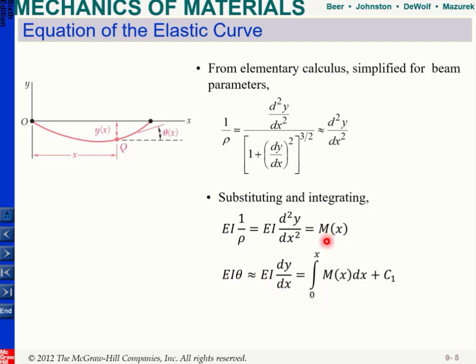And so if you take the integral once, I need to integrate from 0 to x, wherever I want to find my moment. And when you integrate, you will also get one constant. And then if you want to find y, I need to integrate one more time. So I need to do a double integration of the moment. And from here I will get c1x, and then I will get another constant. So if you want to find your deflection, you need to use this equation, and this is called the equation of the elastic curve. It will give me, at any x, what my deformation amount is.